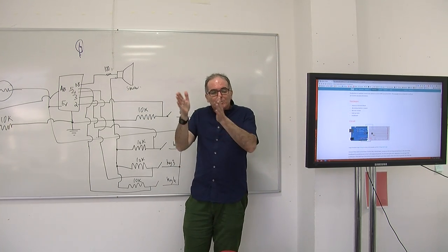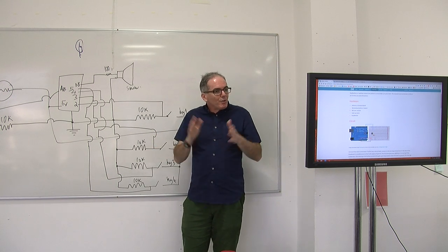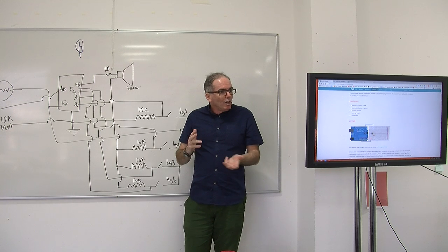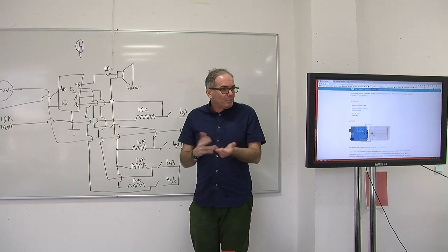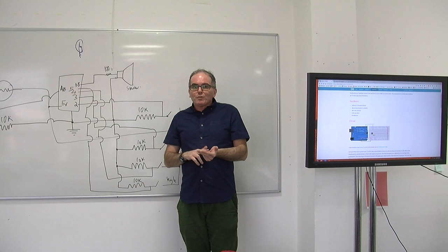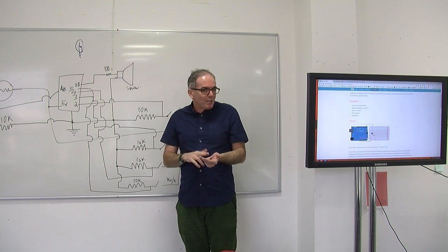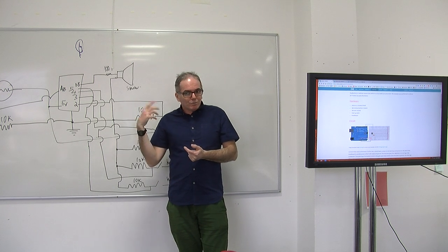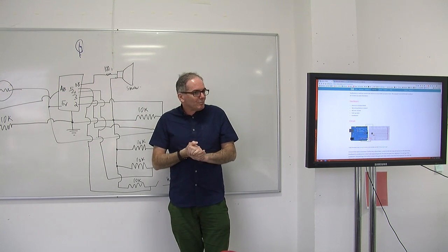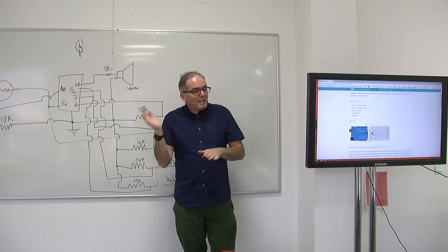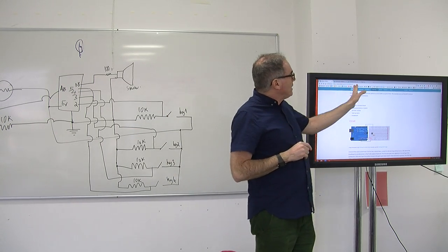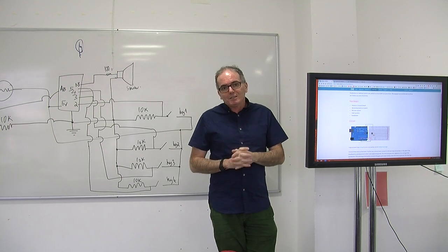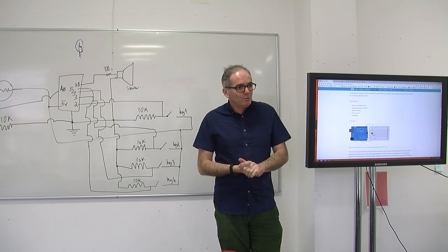In this case, we said, well, we need a keyboard with 4 keys and a change of pitch according to the light. So we need to find something that beeps to make our music. We need to find something where there are buttons to make our keyboard. And we need to find something with a light-dependent resistor to check what light intensity we have. Okay? We then find 3 examples on the Arduino website, which is always the best way to start. If it's on the Arduino website, let's just use that.